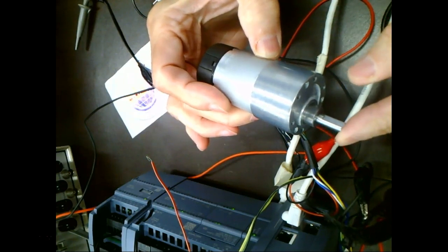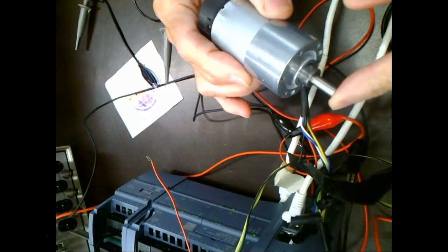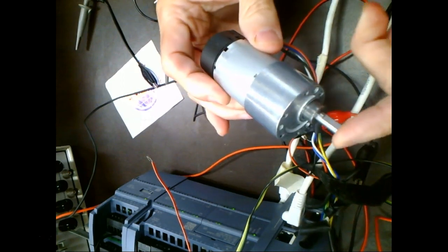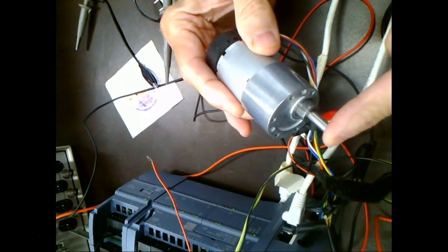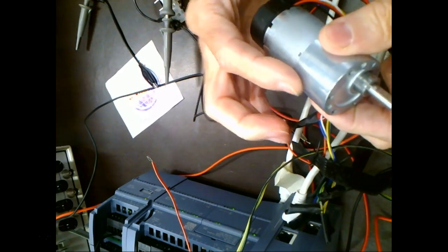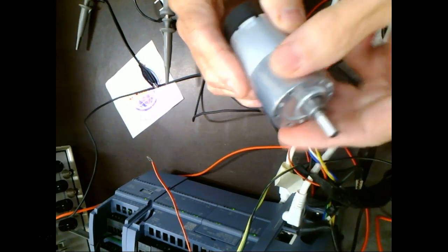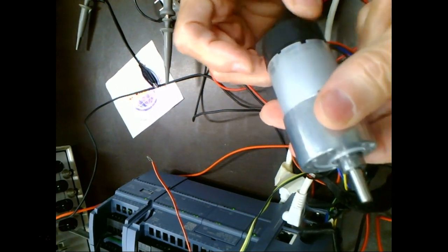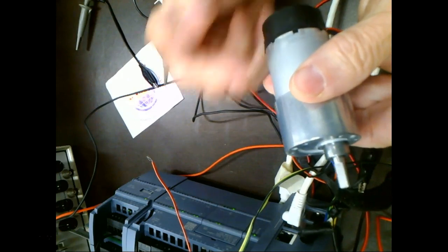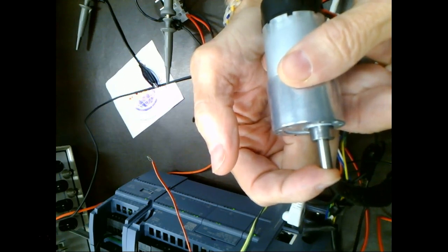Now what we're trying to do is we're trying to see the speed of this guy right here. We're not trying to see the speed of the motor, because this is the end of the motor that's doing work. Okay, do y'all understand that? So what happens, it goes through a gearbox. It's 131.25 to 1. So what that means, this guy over here turns 131 and a quarter turns for this guy right here to turn 1. Everybody understand that?